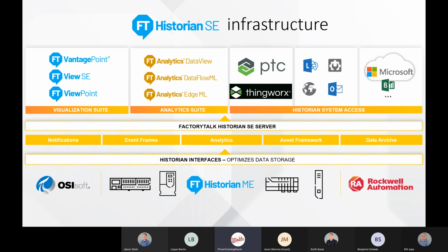And in addition to providing preferred connectivity to Rockwell, the Historian system includes several third-party Pi interfaces for connecting to non-Rockwell data sources. So whether you have OPC DA for third-party control vendors, there's also an ODBC connector. We can connect into a database. If you want to use them in conjunction, you can also connect directly to a database with FactoryTalk Historian. There's an XML file importer to bring in manual data. You'll see XML used if you want to interface some charts with